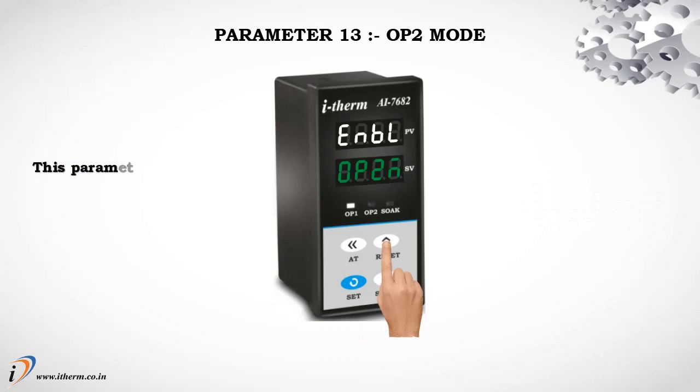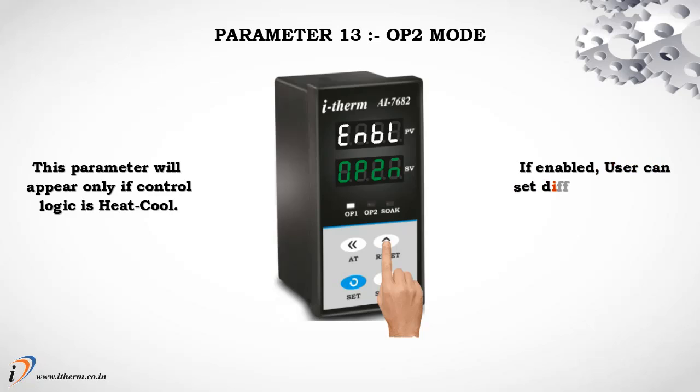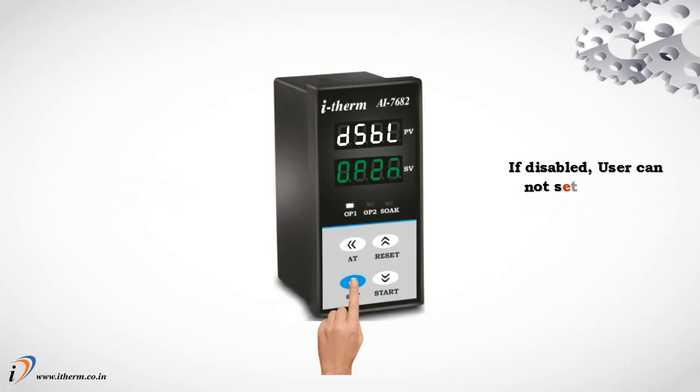Parameter 13, Output 2 mode. This parameter will appear only if control logic is heat-cool. If enabled, user can set a different mode for output 2 in the user list. If disabled, user cannot set a different mode for output 2 in the user list.